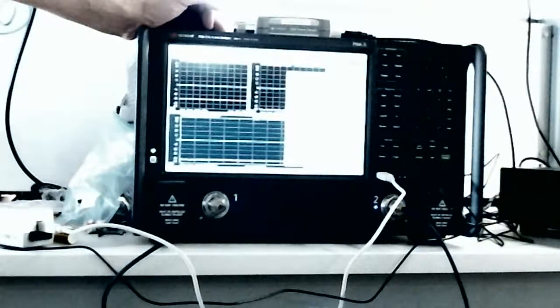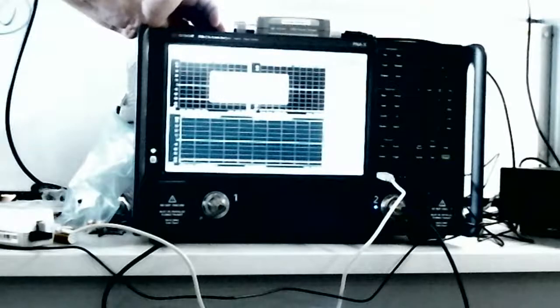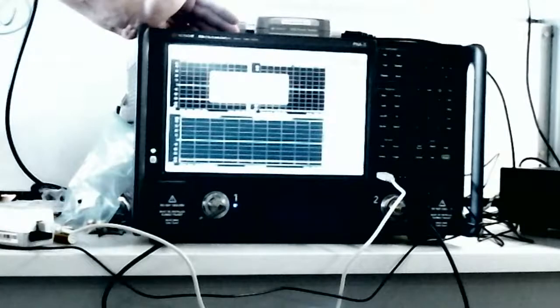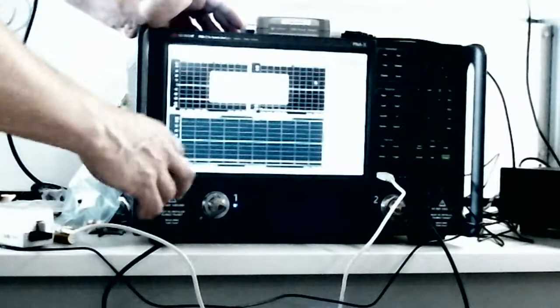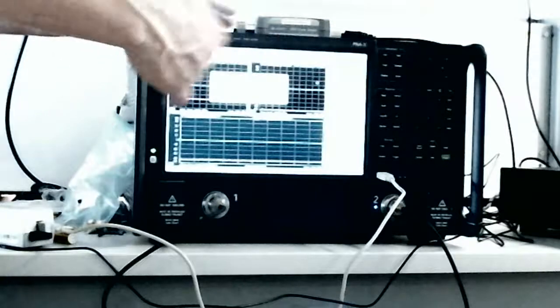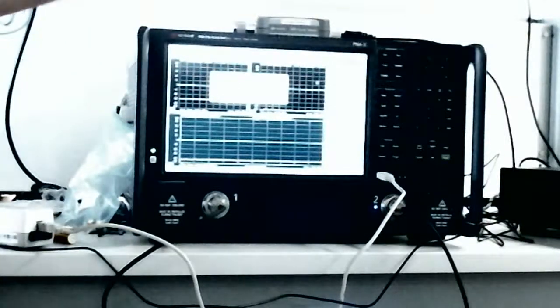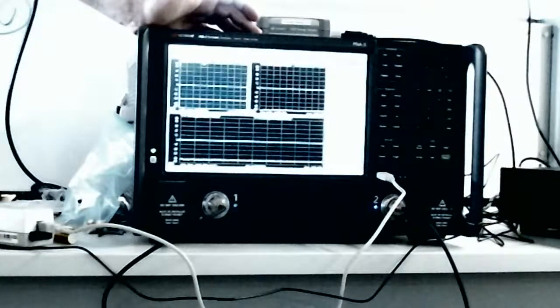So arbitrary impedance we can. Yeah, so you can see under port Z, it tells you R plus JX. So it uses that format. And you just have to click enable. There, you can have port 1 be one impedance and port 2 be a completely different impedance. There's no tie where they both have to be the same. It's completely independent.